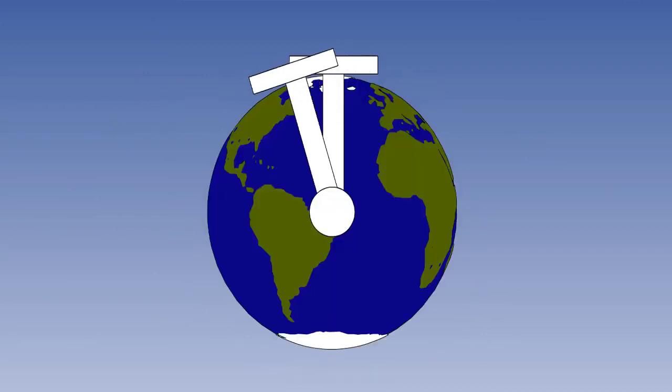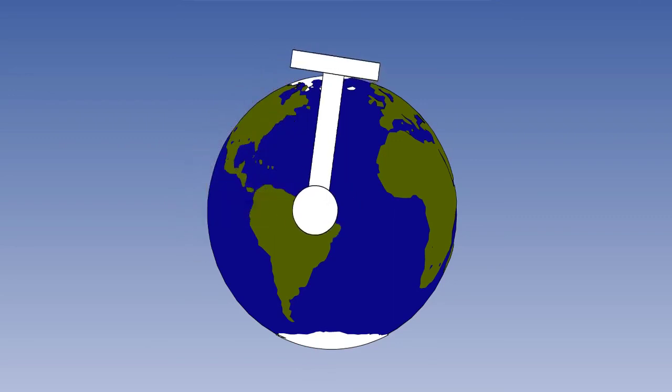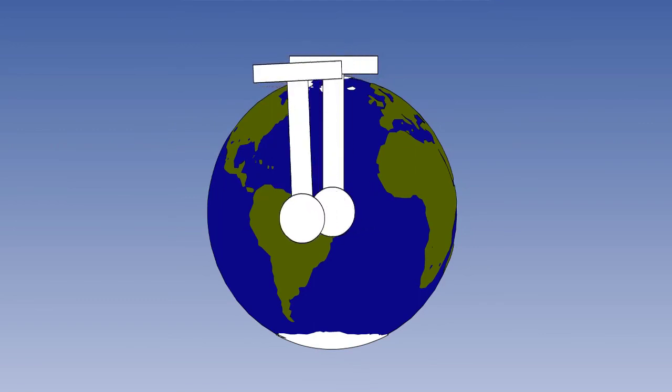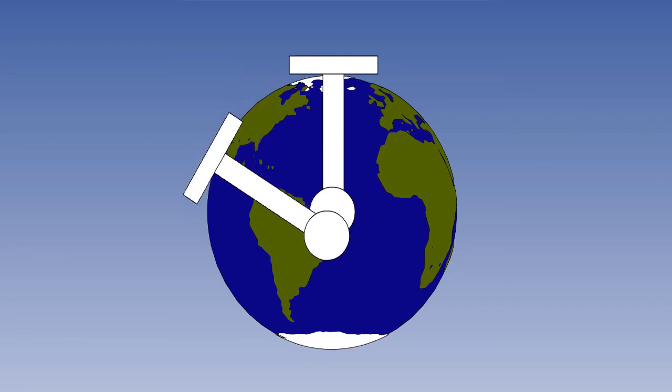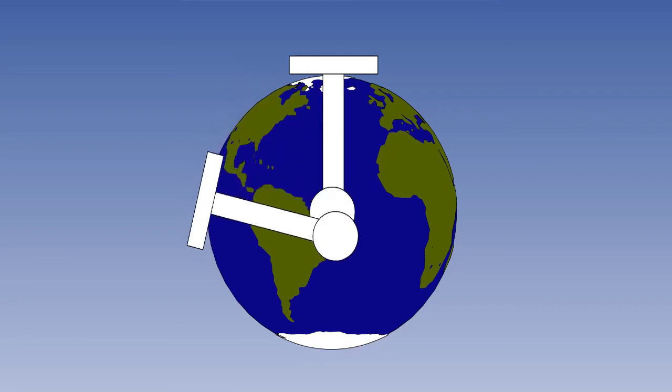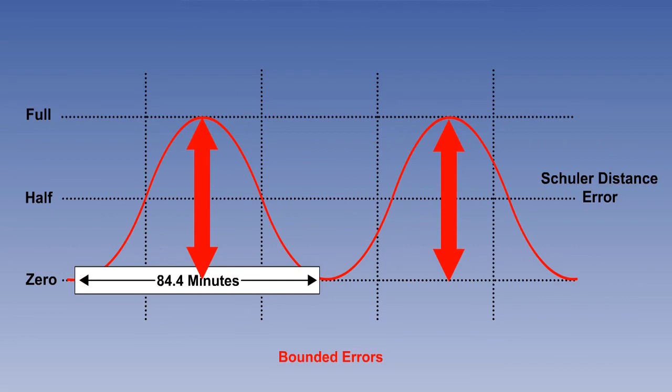We reminded ourselves of the pendulum analogy for normal platform stabilization, and then extended it to include the platform not being level at the start. The Euler period is always 84.4 minutes, and the maximum displacement at the successive 42.2 minute points is always the same.